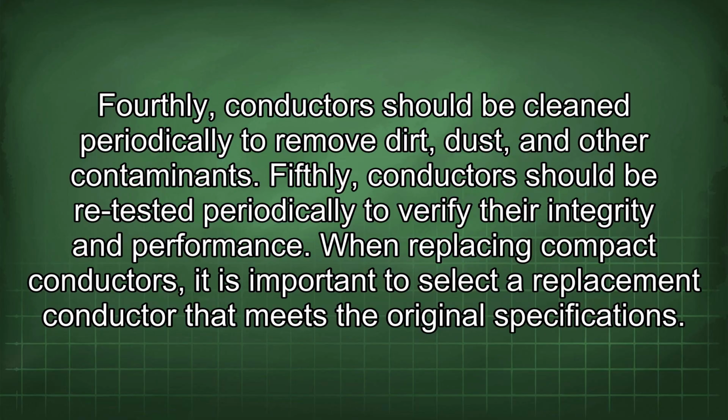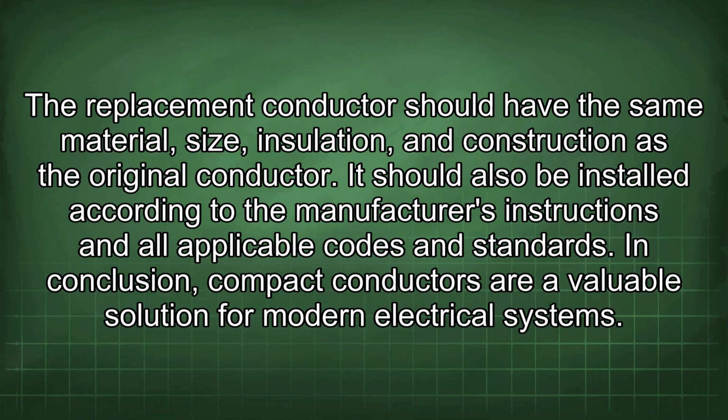When replacing compact conductors, it is important to select a replacement conductor that meets the original specifications. The replacement conductor should have the same material, size, insulation, and construction as the original conductor. It should also be installed according to the manufacturer's instructions and all applicable codes and standards.